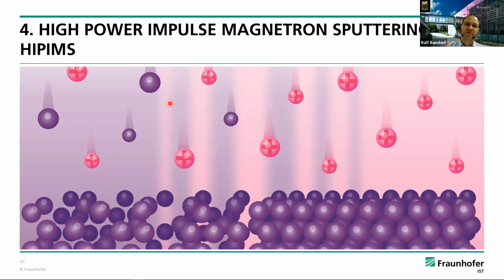If you go to pulse sputtering, you increase the plasma density, you have with the pulsing and switching some hot electrons, a lot of plasma physics, and in the end you end up with some higher energetic particles, what Günter mentioned, also leading to denser films, to harder films, depending on the shape that you have.